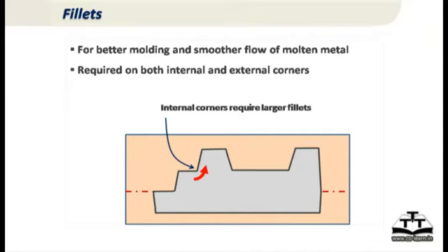But this leads to another complication which we'll see later. The more generous fillet you put, the more you'll find it becomes a hot spot there. But we will worry about that later and see how to fix that. But first, we need to make sure the metal fills more smoothly.